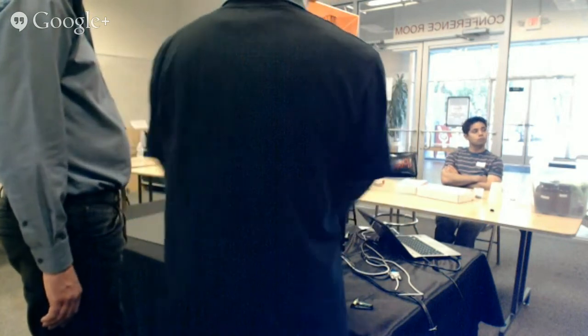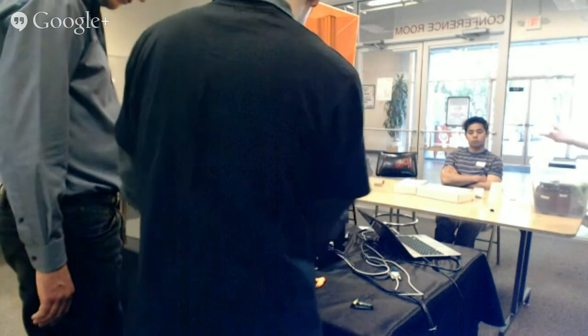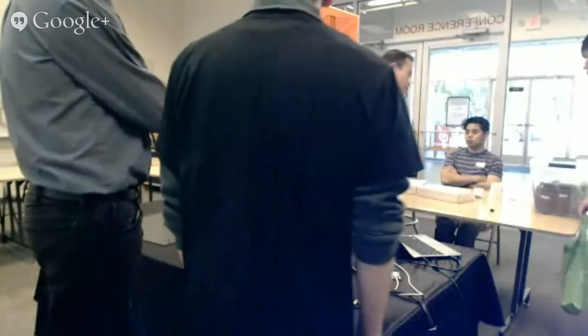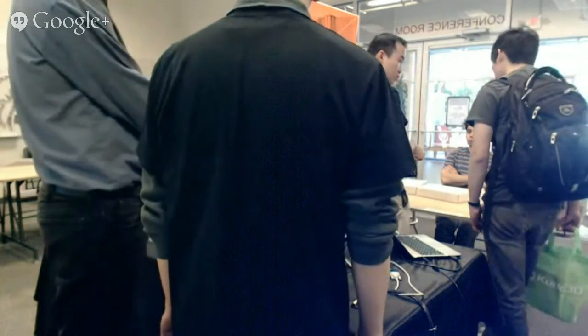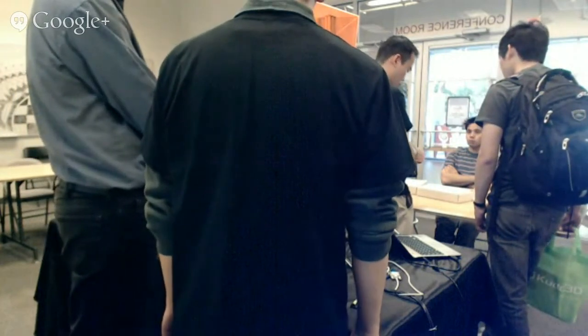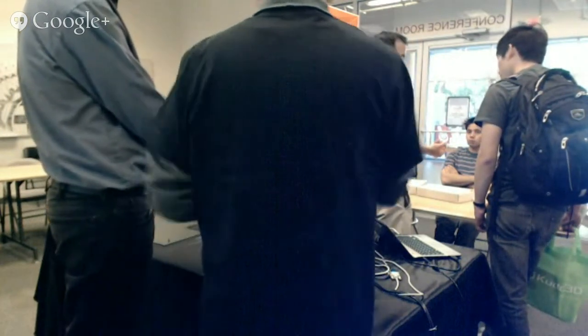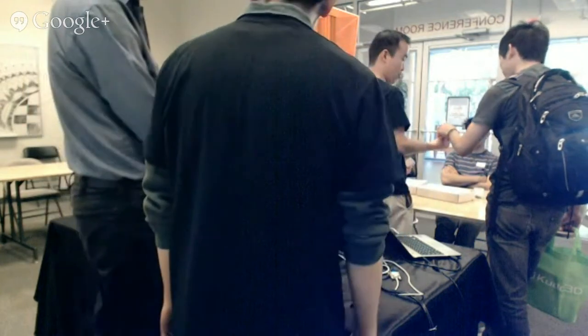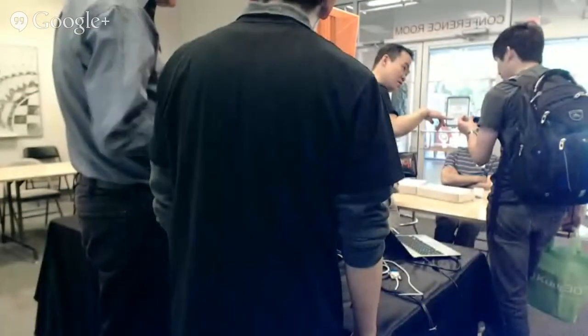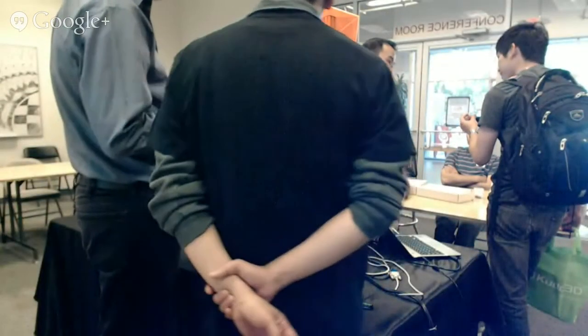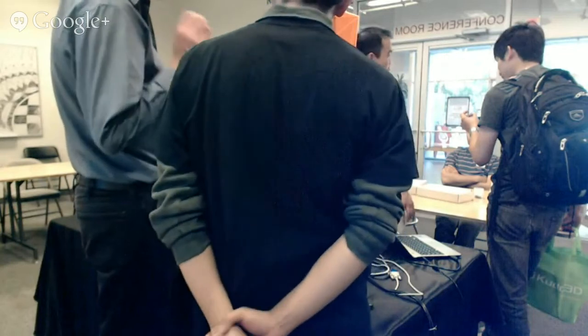For instance, if I were printing it, I would print this part first. Definitely this has the most surface area, this end has less. If I were to print it like this, I still have a couple of really solid layers here, so I would probably tilt it a little bit like this. And then that's when problems start happening, because when I start tilting it like this, this becomes concave. So this edge is built in the middle of nowhere in space.